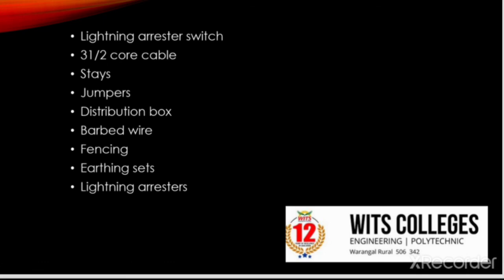The next one will be stays. At least 2 stay sets are provided to support the poles. Then distribution boxes. The low tension supply of the distribution transformer is fed through a distribution box, which consists of a fuse unit.